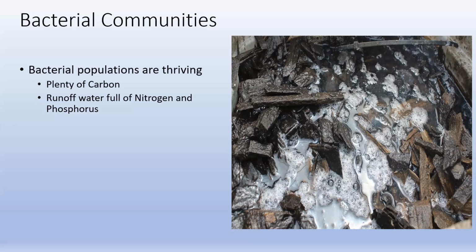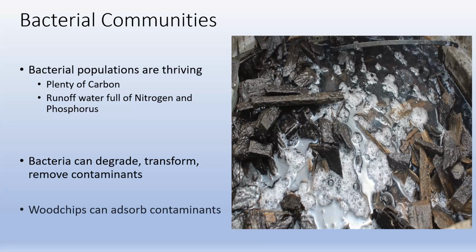And something that we really see come out of it is this huge growth in life. So you can see the bubbles, that gas as these bacteria are respiring, that's pushing out all this gas there. And you see how it's just teeming with this bacterial life. So these bacteria are capable of degrading, transforming, and removing certain contaminants as they go through. We got this very robust population in there that's just super active, and they're going to take care of a lot of these contaminants. The wood chips itself are also capable of absorbing contaminants, right?